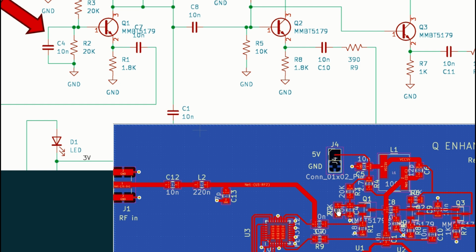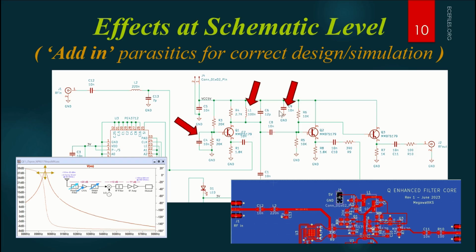There's a resistor in parallel with it, R2, and I could have been silly and put it close to the transistor, but that's bad. We need the bypass capacitor in this position, so that's why the resistor's over here. Similar things can be said about supply bypass capacitors. There's one here, there's another here. At the schematic level, it looks dumb, but we know now that this one is probably here to locally bypass these two transistors, and it's buried down here, whereas this one is over here.